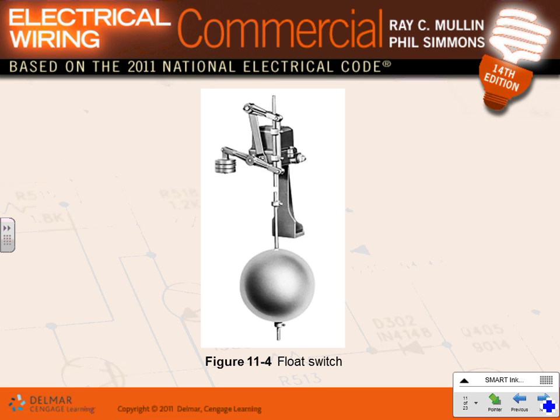Floating switch, you guys have seen a floating switch. If it keeps going up, it means it's filling that little hole of water, right? It triggers a couple of switches here and starts the pump. When it goes down, it opens contacts. Everybody knows how this floating switch works, right? That little ball keeps going up. It's like the thing in the bathroom they flush. It's called the float, the floating switch. So it goes up, it triggers on, and goes down, triggers off. It gets you on at a certain level, and gets you off as it goes down to a certain level. Mechanical interface.